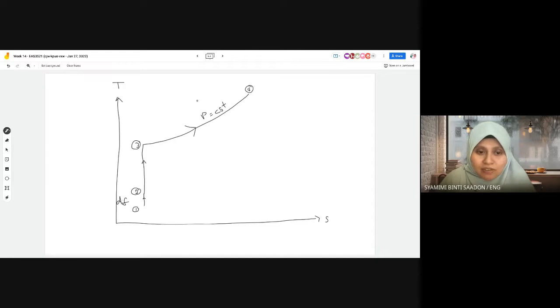Next, after combustion chamber, so this is CC, combustion chamber, this is compressor. You have to know all the components in the basic jet engine. You are in the aerospace engineering program. So after combustion chamber, which component? Turbine, okay, turbine. Just like the power plant just now, you have turbine. So turbine like this, a straight vertical line. With the turbine, you decrease pressure and you decrease temperature.